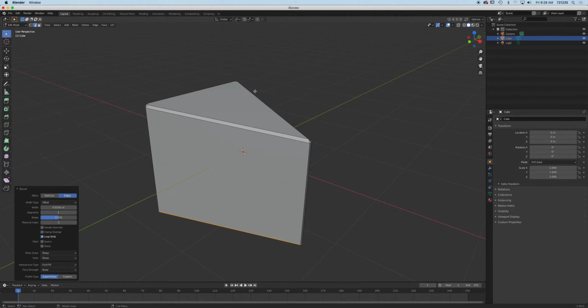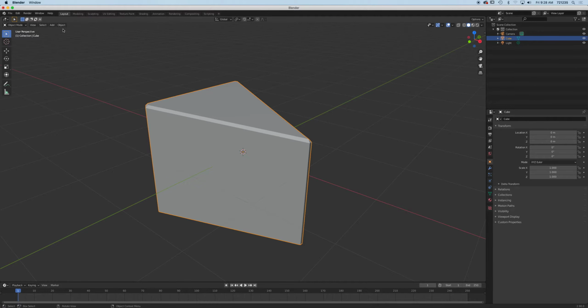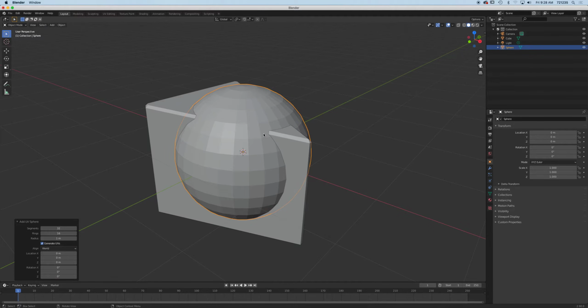Oh. All right, so what do we use for Swiss cheesing this one? Boolean. All right, so we need multiple sphere shape sizes, okay? So I'm going to go with UV sphere. It's very faceted, agree? It doesn't have enough resolution, right? So I'm going to double that with rings and segments over here. So I'm going to go with 64 and then rings of 32, okay? Keep in mind when you increase the resolution on Boolean, it keeps it, because if you have to apply another modifier, then you would lose that, okay?